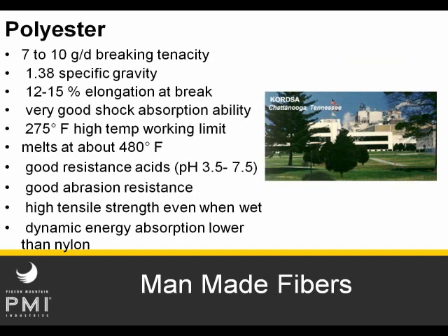Note, however, that polyester as a fiber does have only about half of the inherent elongation that nylon does. Other characteristics, including strength and heat resistance, are relatively comparable to that of nylon. Some rope users select polyester for its chemical resistance, but even though polyester is more resistant to acids under a high-intensity exposure, nylon is more resistant to alkalis. So keep that in mind.